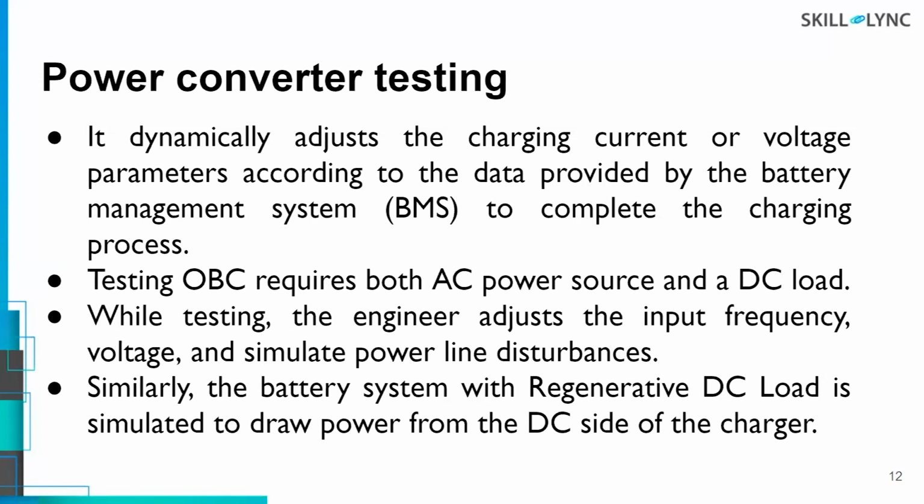So when you're charging, every cell should be charged up to 100%, and not one single cell is left alone at 90% or 95%. How this is done is you can go and check your battery management system data. Charging current is something which comes from the onboard charger, and your BMS will decide whether it is properly giving the charge, whether it is giving it at the C rate which is mentioned for your EV.